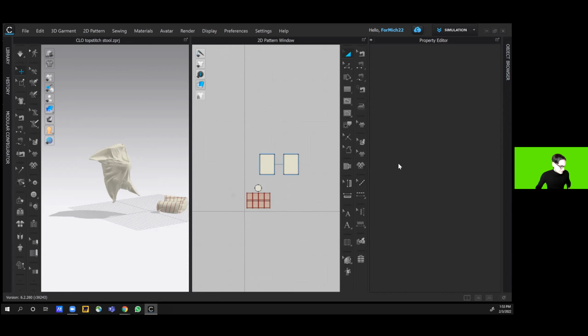Yes, this one that I'm highlighting, I think you can see, is really important. When you use pressure, it's actually putting pressure inside of the space between the textiles. And so if every seam isn't closed off, you'll know because when you run the simulation, the garment will shoot off like a rocket because all the air is escaping from one point. So you actually have to keep it airtight and pay a lot of attention to the seams and closures that you're making, because the air will escape.